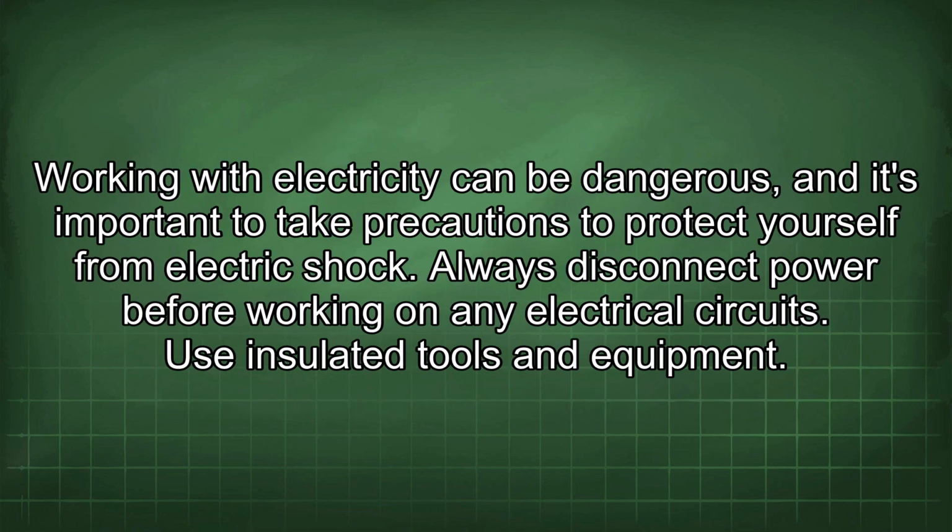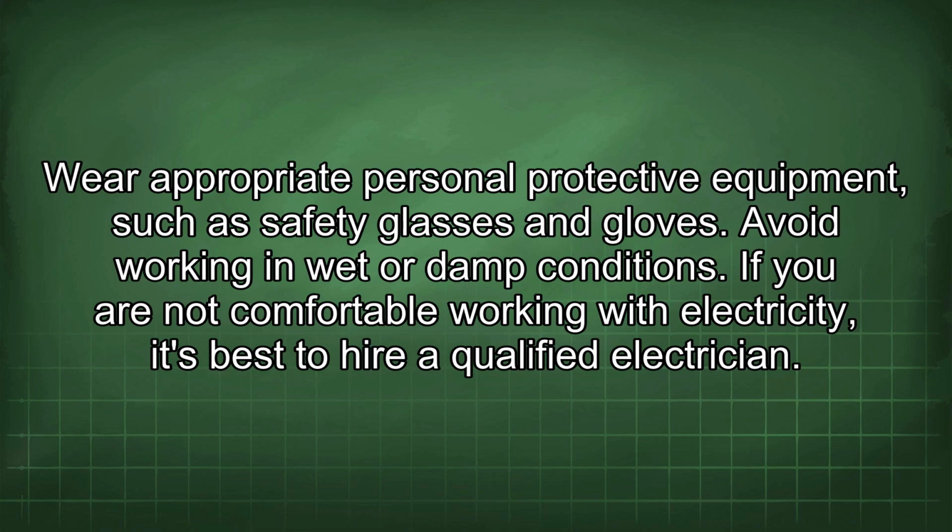Working with electricity can be dangerous, and it's important to take precautions to protect yourself from electric shock. Always disconnect power before working on any electrical circuits. Use insulated tools and equipment. Wear appropriate personal protective equipment, such as safety glasses and gloves. Avoid working in wet or damp conditions.